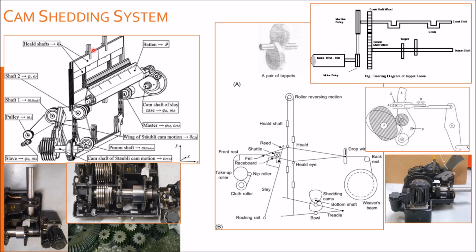So in this slide I want to mention that for two cams we have to reduce the drive, the motion, the rotation of our bottom shaft, camshaft, one half, that is one half of the crankshaft. And if we increase the cams, we will have to reduce its motion further. More the number of cams, more the rotation we have to reduce.